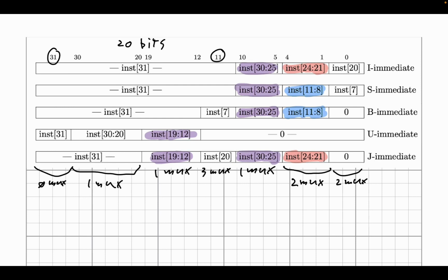Well, in that case, we want to do that to as few bits as possible, because that's going to take up extra layout space, and it's also just going to require more current, right? And that's going to be bad for power consumption. The reason for the last bit of bit swiveling is that it makes it so that there's only one bit that ever gets this extra bit of current coming out of it, and that is bit 31.